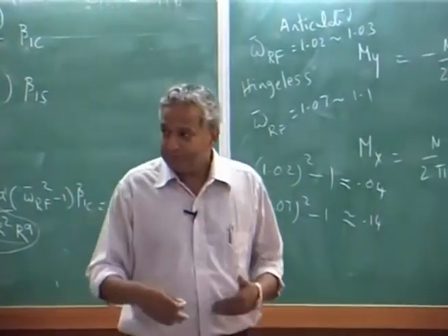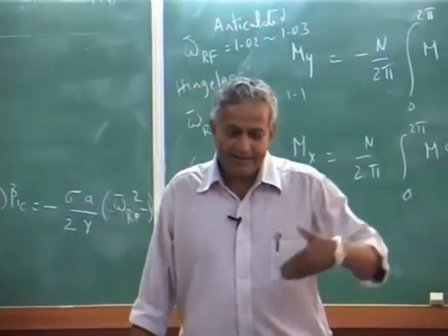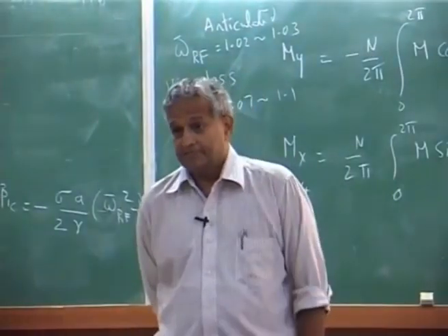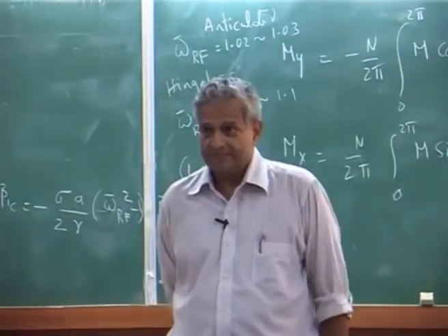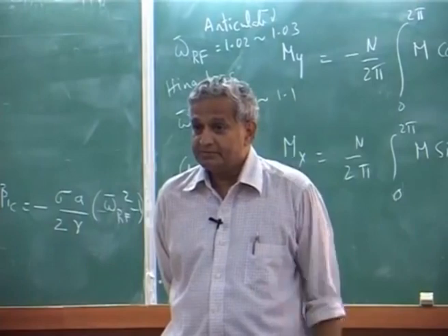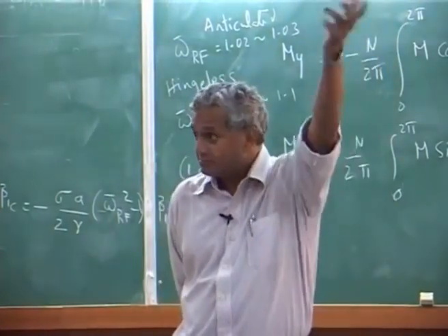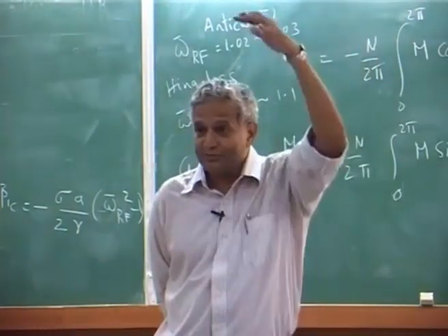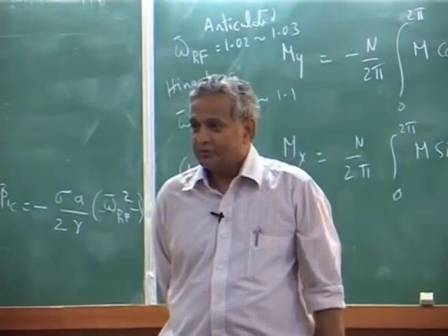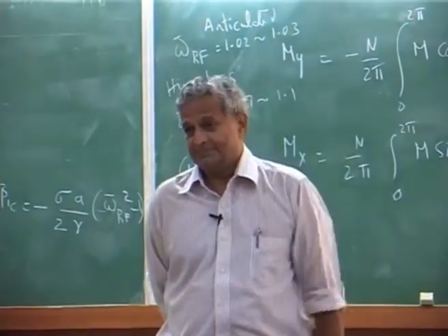They say when I have my flap frequency high, I get a good control moment, but at the same time that means I am transferring a lot of loads from the rotor to my fuselage. So, I will transfer more vibration also.